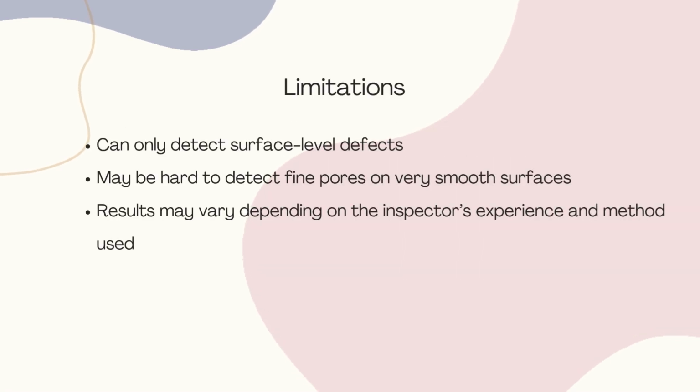This test has some limitations also. It can only detect surface level defects. Then it may be hard to detect fine pores on very smooth surfaces. And next, the result may vary depending on the inspector's experience and method used.